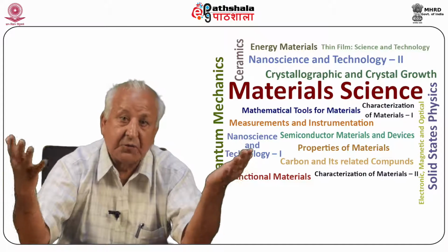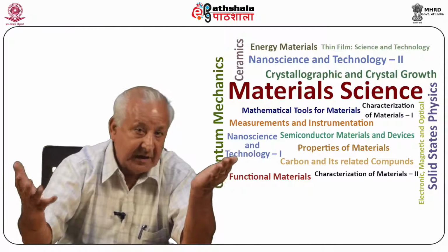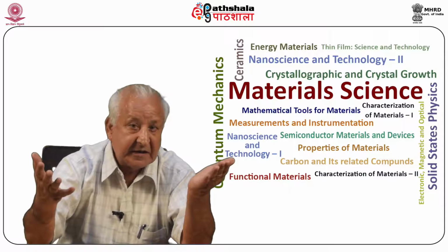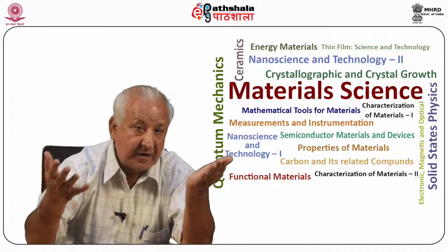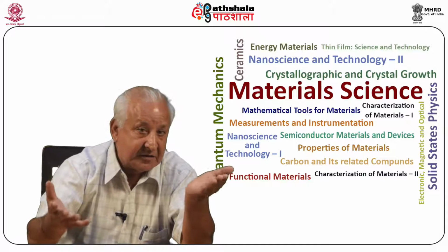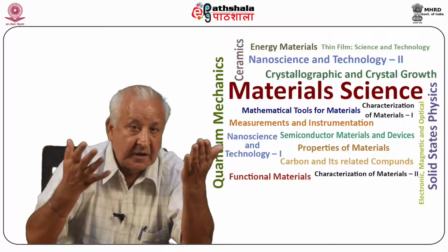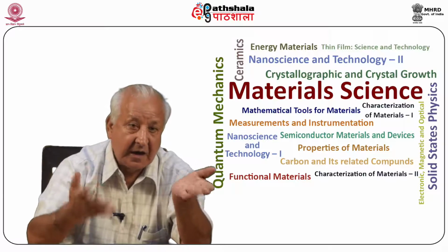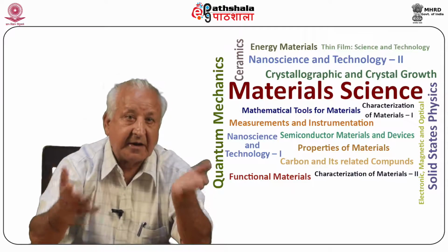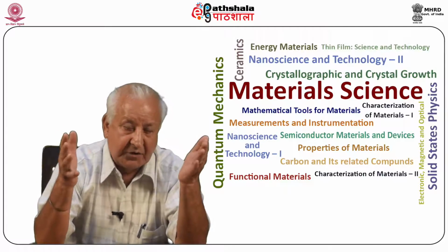The molten zone floats below two solid parts of the rod, held in place by surface tension. Since it does not require a retaining crucible, the technique has the advantage that possible contamination from the container is avoided. It is used for the growth of silicon, which is the only material grown on a very large scale, around 1,000 tons per year.